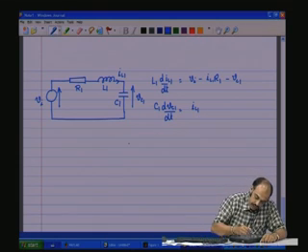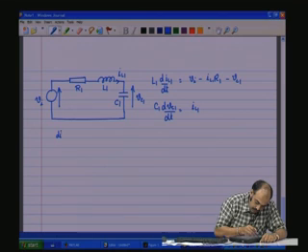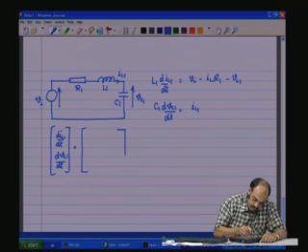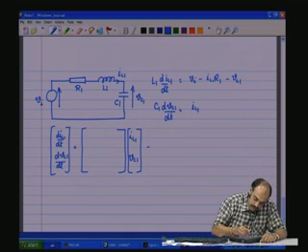So, putting it in the state equation form, you have dIL1 by dt, dVc1 by dt. This is the x dot, x being the state vector. You have IL1 and Vc1 as the state vector plus an input matrix that we need to fill up, Vi.